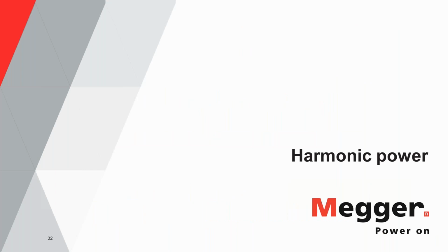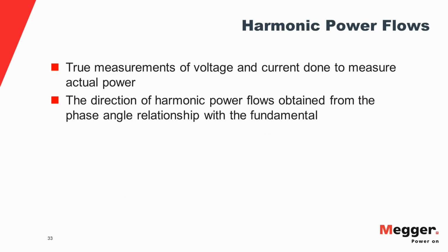So the next section is on harmonic powers. Power is measured by looking at the true RMS values of voltage and current. If you take individual harmonic powers, the direction of the flows differs from harmonic to harmonic. So it's not essentially the same as the fundamental power.